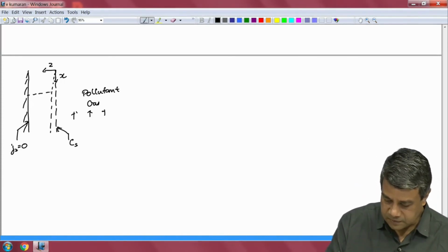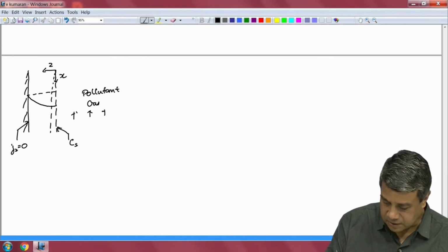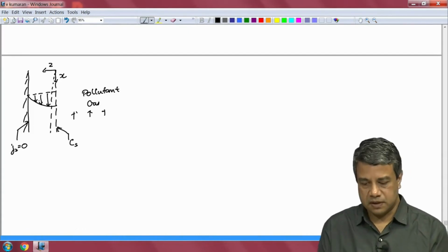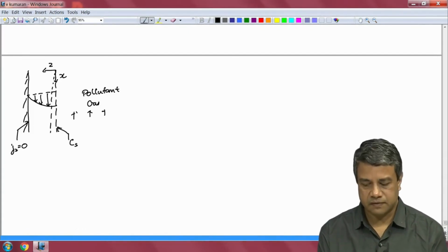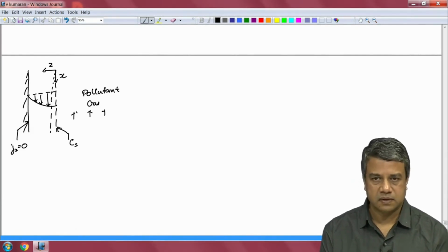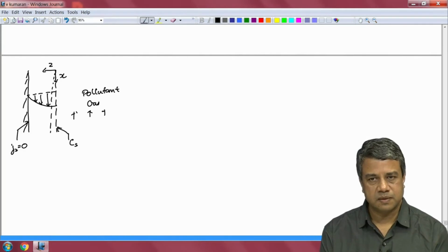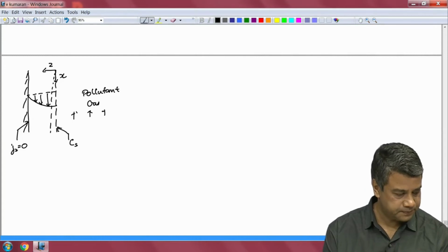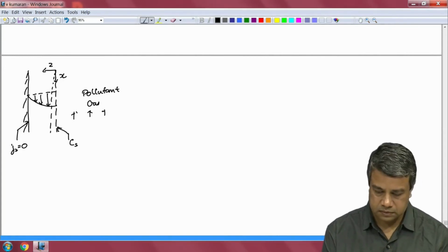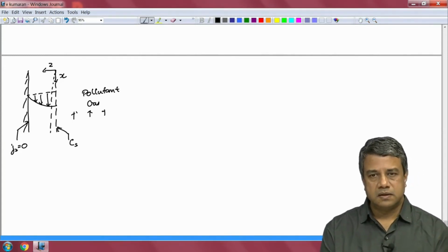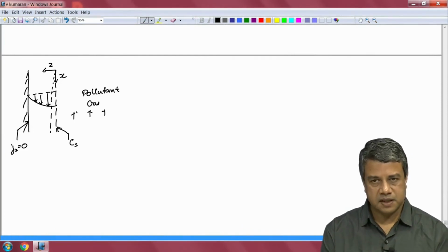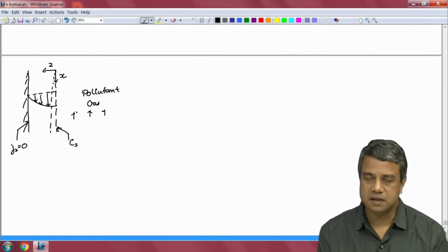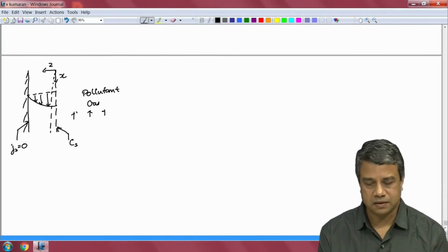And the fluid film is flowing down with a velocity profile that we had already calculated, a parabolic velocity profile, which we had already calculated for the flow down an inclined plane. The same solution will apply in this case if I set the angle of inclination theta equal to 90 degrees. So, here what we have is a spatially varying problem. There is a variation in concentration with respect to both x and z.